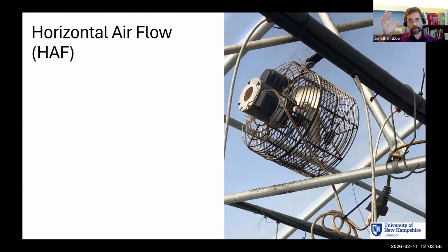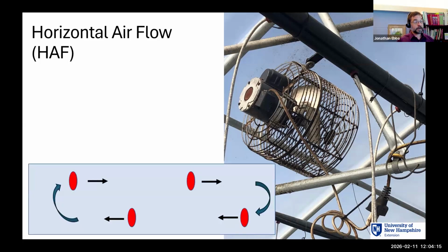But it's important to know you can put all the fans you want inside a house. And if that house is still tight like a drum, we're not cooling, right? So this is all about that airflow and that distribution. So there are obvious benefits to this for disease, humidity, and heat distribution. And I want us to remember we're creating a circuit of air when we use horizontal airflow. Okay, so that looks kind of like this.